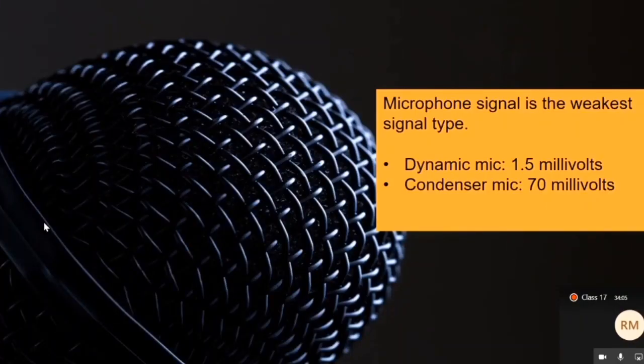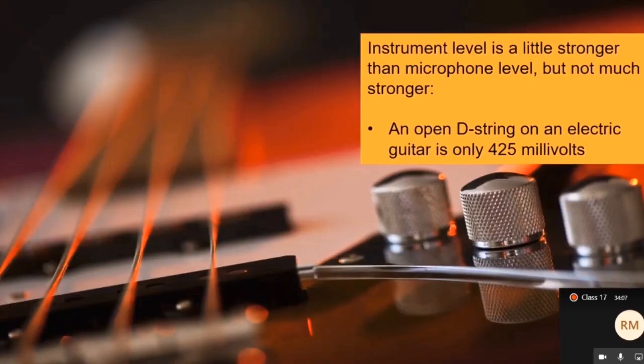Okay, and then moving forward, we have what's called instrument level. It's a little stronger than microphone level, but not much stronger. And of course, you're going to have different instrument levels between your instruments, but we can think of an average here. If you play an open D string on a guitar, all right, that just generated about 425 millivolts.